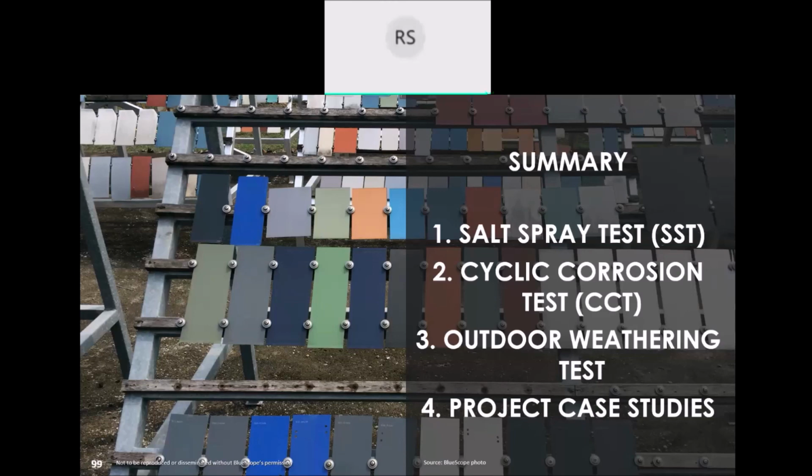If, let's say, it's the exact same environment, for example, if you know that your building is built near the sea, roughly you can estimate that it's a C4, C5 environment by the standards. Then you can do a study. For example, a C4 environment near the sea.